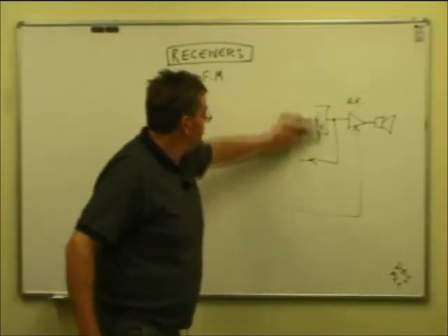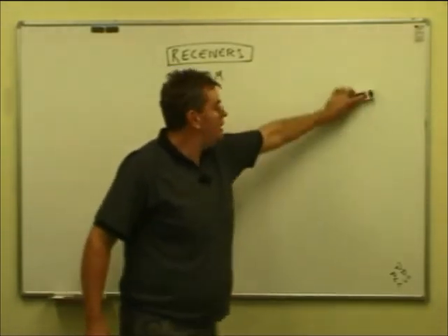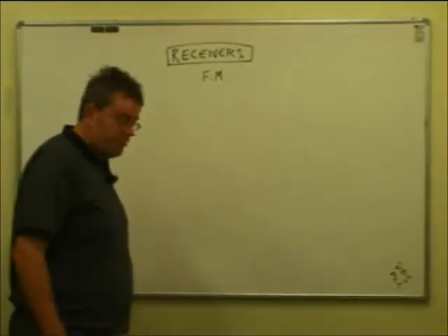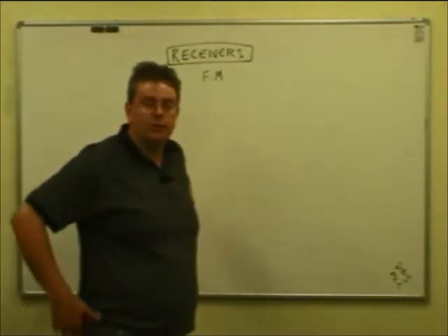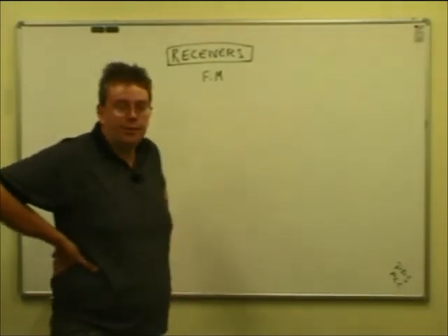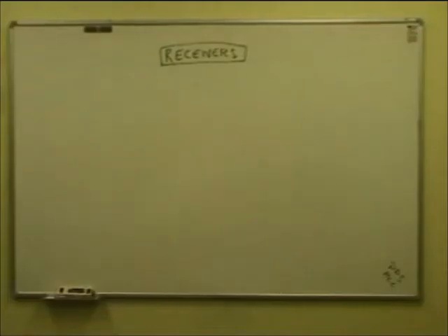Typically that's at higher frequencies, maybe VHF, that one we're just listening to was 146.95 megahertz we were receiving. The intermediate frequency in those handhelds is often 10.7 or 21.4 or something like that. So the local oscillator will be running at quite a high frequency, around the 130 odd megahertz range. Just a final comment about FM receivers.